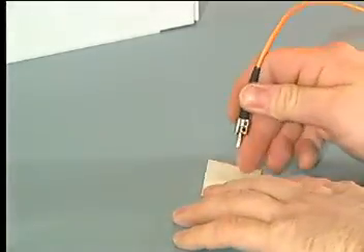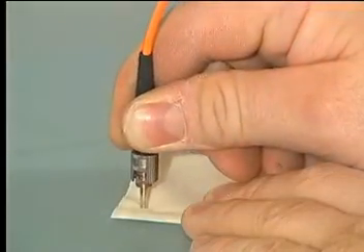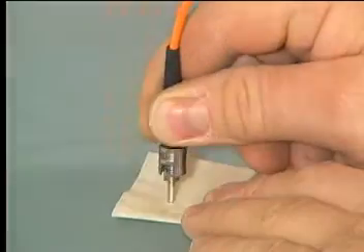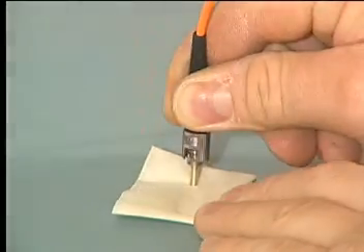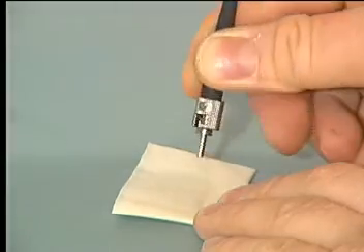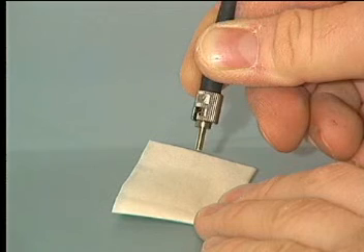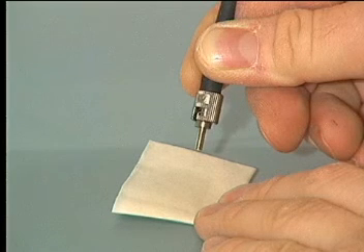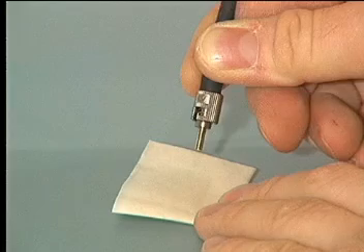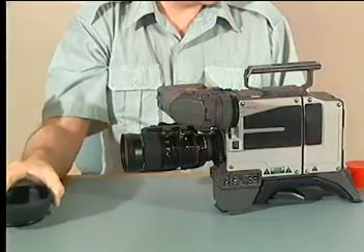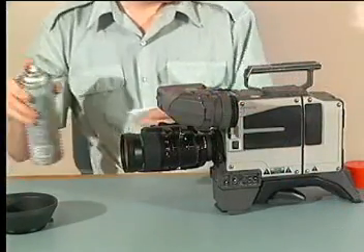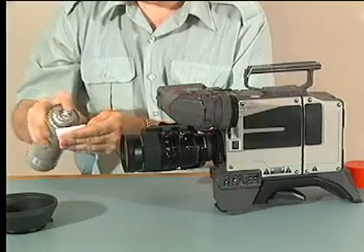The alcohol will evaporate very quickly from the pad, leaving dry lens paper. The connector end should be passed over a clean section of dry paper at least once to remove alcohol streaks on the ferrule. Do not touch the mating surfaces or place the connector on any surface before remating. Connectors used in higher speed systems require more careful attention during cleaning.